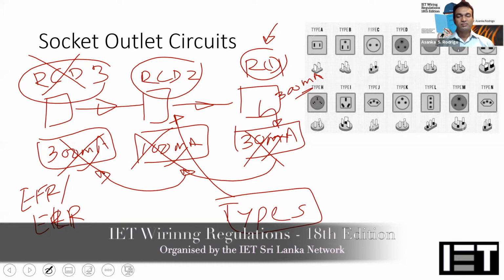Next question is, what is the minimum distance between the generator earth, the transformer earth, and the surge system down conductor? As I said, everything will depend on your earthing arrangement. For example, if you are designing a TT arrangement, for your transformer neutral earth you have to have a separate electrode, and for the generator you have to have a separate generator neutral point electrode. But in some locations I have seen the transformer maintaining a separate electrode, while the generator body earth is connected to the normal electrical installation, so that ultimately the generator runs as a TN system but the transformer runs as a TT system.